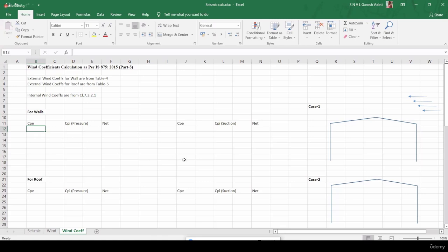We cannot apply the entire wind directly onto the frame. There will be some coefficients: external wall coefficients, internal wall coefficients. We have to apply net wind pressure. How to apply net wind pressure, and what are the directions? And there are sign conventions, plus and minus. How to use plus and minus in STAAD Pro, and how they get different?